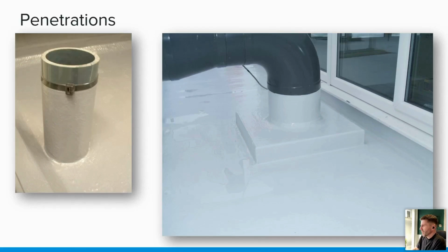So what should good practice look like for a pipe penetration? In a liquid situation, you can see this one on the right here, you've got your pipe penetration, you've got your liquid taken all the way up, and it's protected then by this pipe coming down over the top, on a smaller diameter. A cable tie can be used just to protect the top of that. Jubilee clip cable ties, those kinds of things can always be used just to protect the exposed edge of the waterproofing. But again, that's something that needs to be checked as part of your annual inspections that you should be doing.